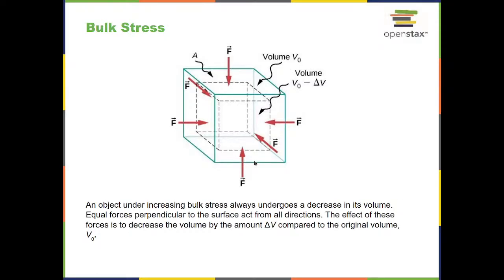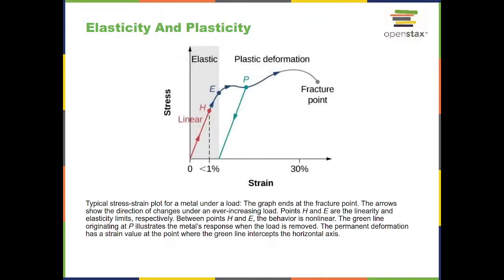Okay, so we've introduced bulk modulus, elastic modulus for compressive and tensile stresses, and we've introduced the shear modulus. One last thing I want to go over, and this is just the last section of this chapter, is that this really only describes the small changes, the small strains and stresses where the behavior of the material is elastic. So essentially where we bounce back without changing the original shape of the object.